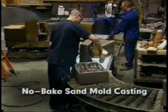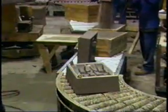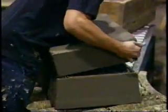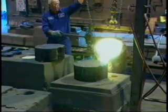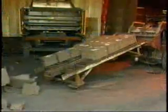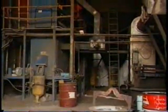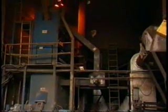No-bake sand molds, also known as air-set sand molds, are a mixture of sand and a resin binder. This mixture is packed around a pattern and sets quickly at room temperature. No-bake sand molds are extremely strong, erosion-resistant, and provide good dimensional accuracy and casting finish. Casting shakeout is excellent, and reclamation of the bonded sand is practical, although it is more costly than with green sand.